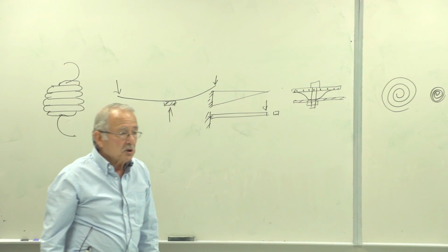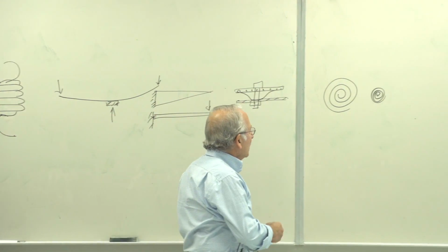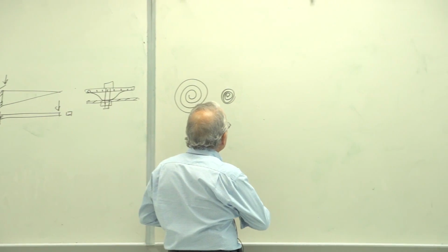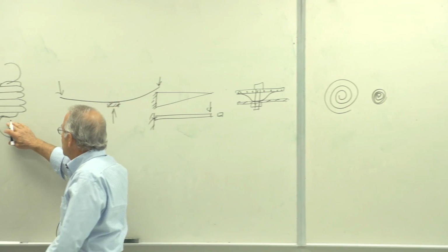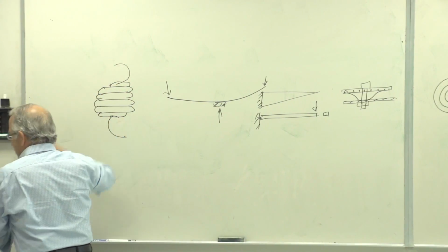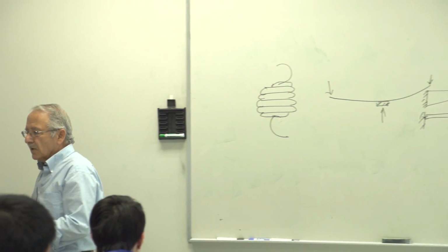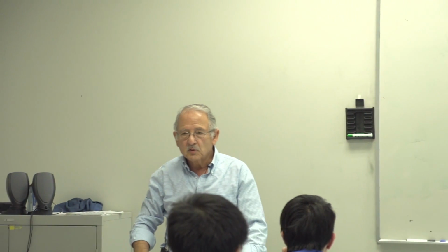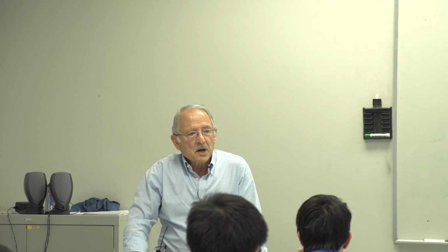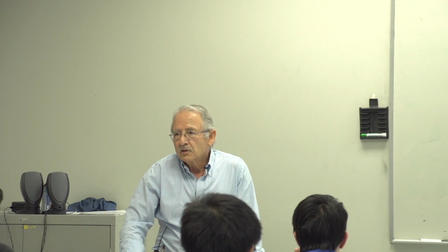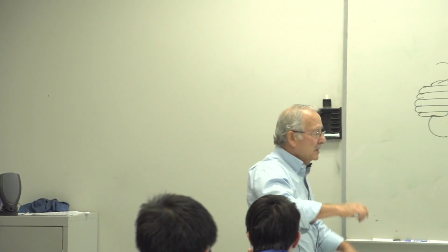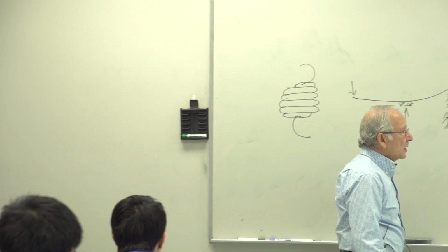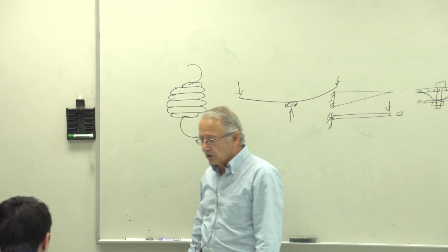The same thing can be done in torsional springs, which look very similar to tension springs, except that you put torques on them. If you get a chance next time you're in Home Depot, take a look at mouse traps. They use that kind of spring. So that also relates torque to an angular deflection.